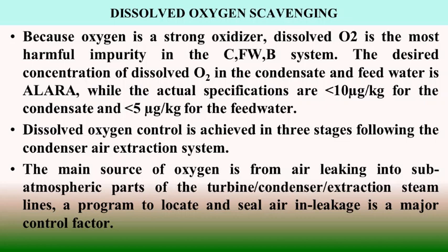With the combination of heat and large surface area imparted to the water, there is very efficient stripping of dissolved gases including oxygen in the deaerator, and that reduces the dissolved gas availability below 10 microgram per kg, or ppb, and nitrogen is also removed if there is some air side nitrogen contamination.